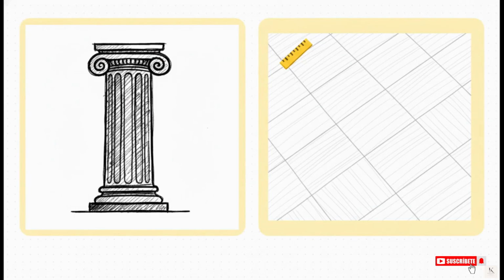And this brilliantly illustrates the entire core philosophy behind CAD line weights. On one side, you have the undeniable physical presence of a structural column drafted at a heavy, bold 0.40 millimeters. On the flip side, you have the lightweight detail of a material hatch drafted at a whisper-thin 0.09 millimeters. This hierarchy is exactly what prevents visual clutter. It instantly tells your brain what holds the building up versus what is just a pretty tile pattern on the floor.